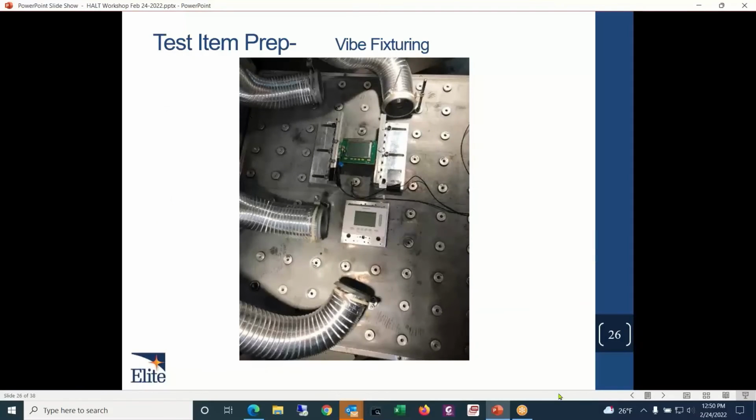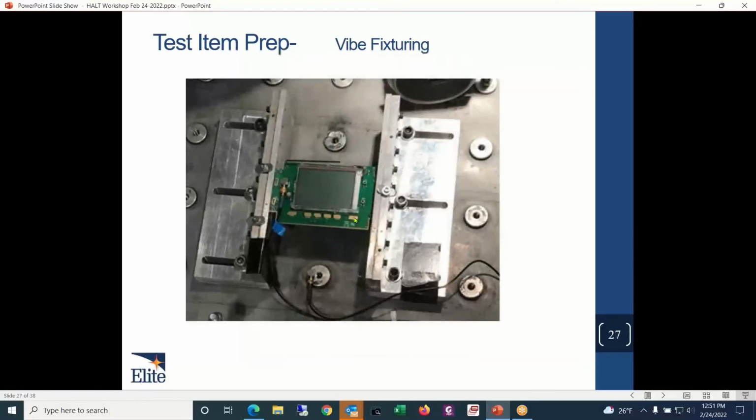So what we look to do is consider not only the fixture size, but are we going to test a product just as a printed circuit board, or the product in its housing? So again, if we take the printed circuit board out of this thermostat, we try to test them in a comparative manner, side by side. How effective is vibration getting to this printed circuit board versus how effective is acceleration getting to the printed circuit board when it's mounted in this little thermostat here.